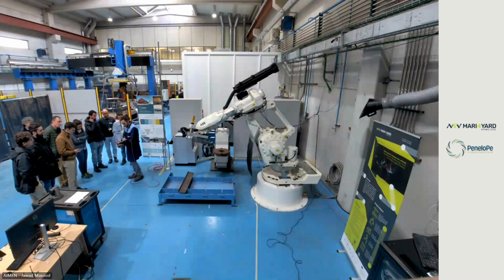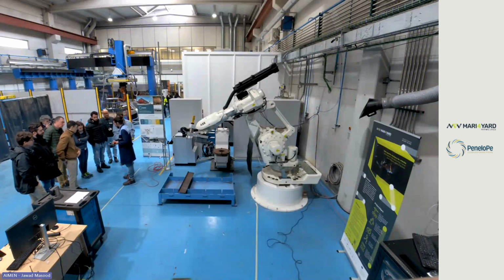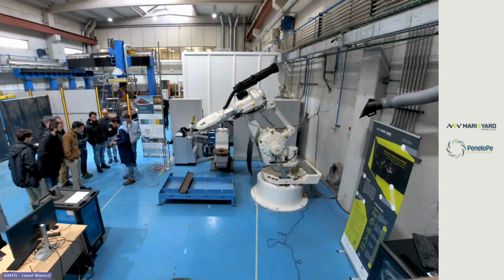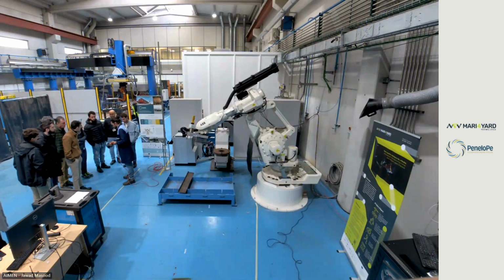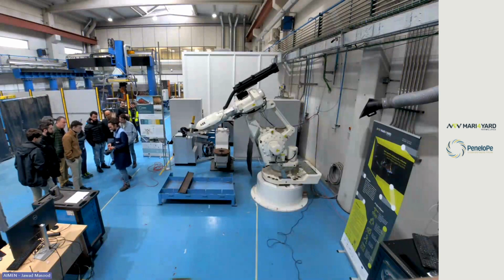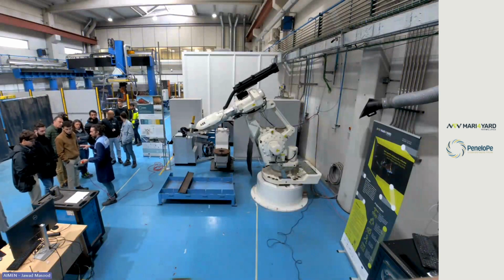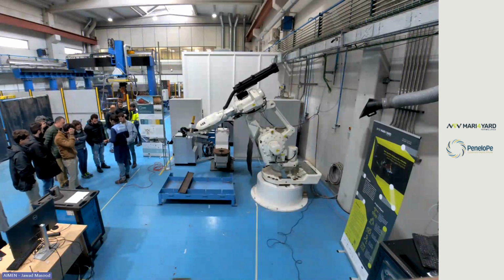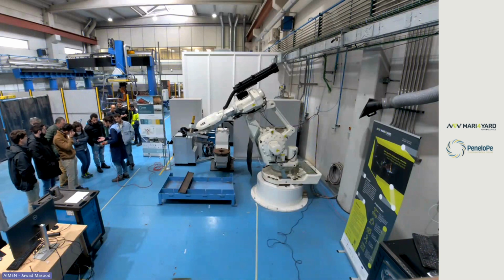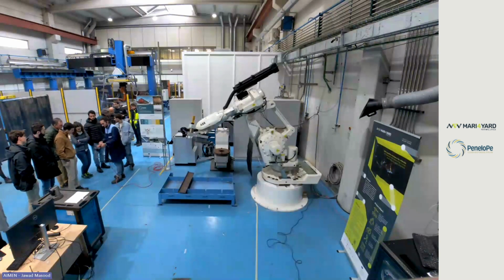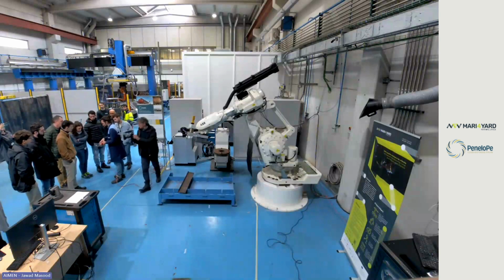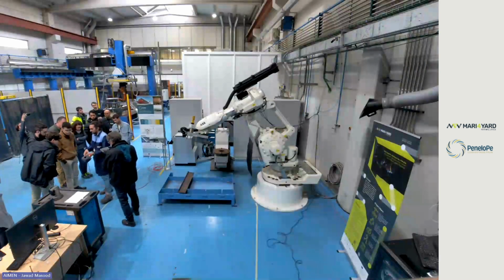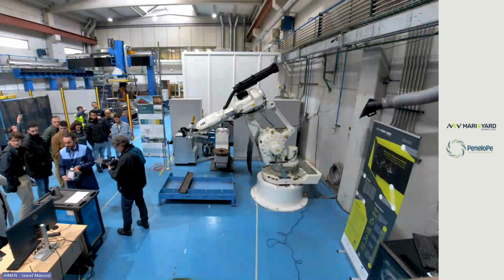For doing that, I'm going to add the set of instructions that ABB offers me. I can open here this palette of instructions. They are grouped in different areas depending on what we want to use. Now we are in the most common instructions. We can see here the move L, for example, and move G, set, reset, if, etc.